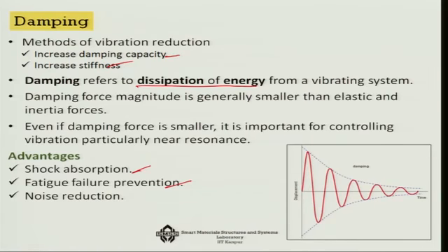So, this is typically an under damped curve, as you can see, and this is under viscous damping, and you can see that the response is coming down exponentially. Okay. So, as the damping increases, this will be more and more, and there is something we call the settling time. That means, in comparison to the initial value, plus minus about 2 to 5%, when the initial amplitude comes down to within say 2 to 5% level, we say that the vibration has damped down. So, there are various ways in which we can quantify the damping.